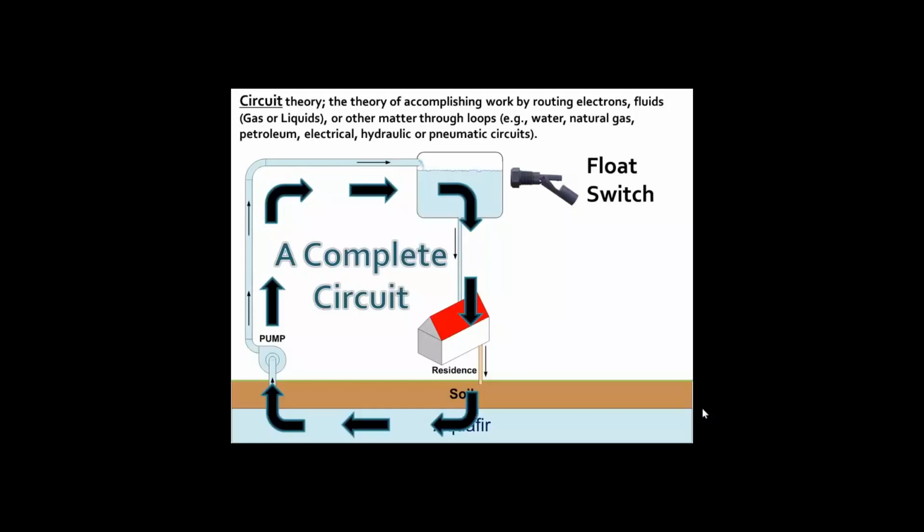So as the water lowers in the tank, the float starts to angle down, and when it gets far enough down, then gravity carries the weight inside of the switch bulb to close the switch. And then, of course, it turns on the pump, the water pumps back up, it starts floating back up until it's above level and tips in the opposite direction, and the weight slips the other way and opens the switch.